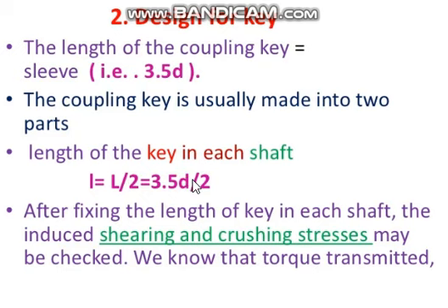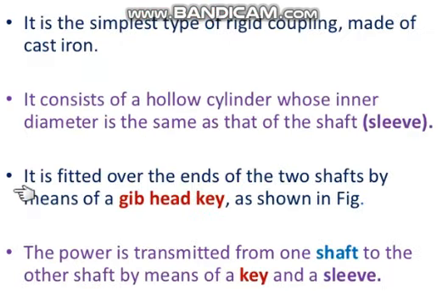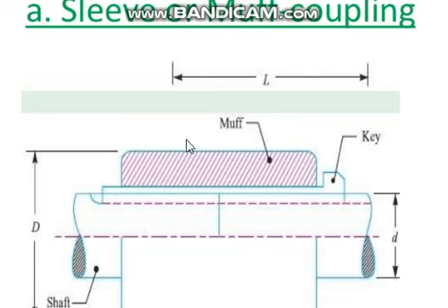So it is staggered at a 90-degree angle. 90-degree angle means, if this is a side view, one circle, if one key is here, the other will be at 90 degrees here. As if x, y axes are like this, if one key is here, the other key will be here. Otherwise, in the front view, if one key is here like this, another key will be here like this.